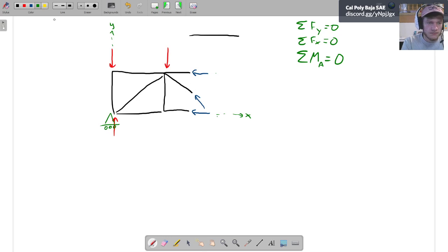We can see, okay, I'll call this A, call this B, call this C. And if I'm smart about how I do this, I can already tell from observation that B, C, and A are the only forces that have any component in the x direction, right? So if I were to write out my sum of forces in x equation, I would get something in terms of A plus something in B plus something times C equals 0. And for all intents and purposes, this equation isn't very useful to us.